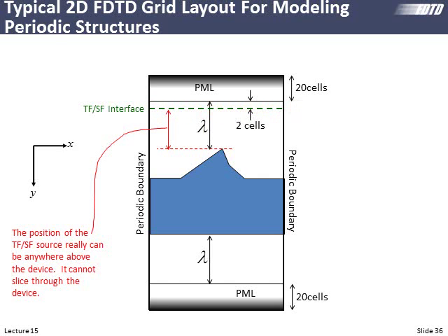We will be injecting a plane wave source. Plane waves only exist inside homogeneous materials. So if we slice through our device and tried to inject a plane wave, we'd get a very crazy result from that. Anyway, this is our grid strategy and how we'll do things.